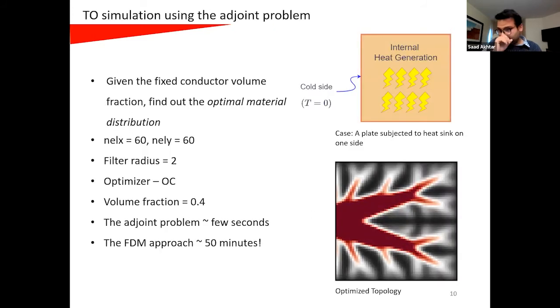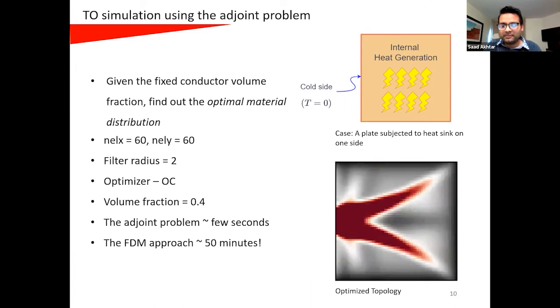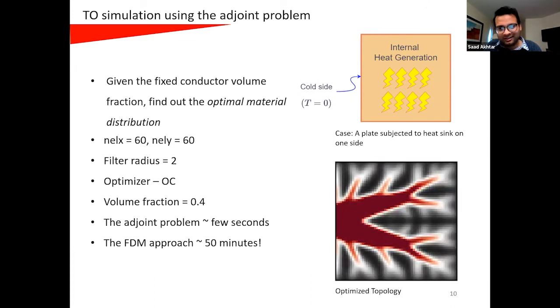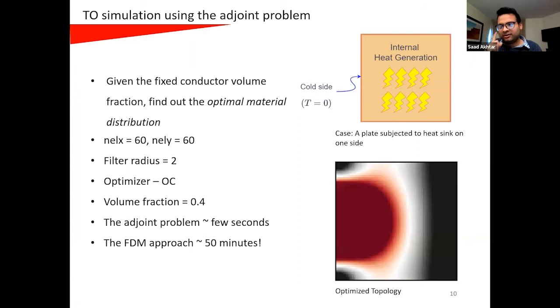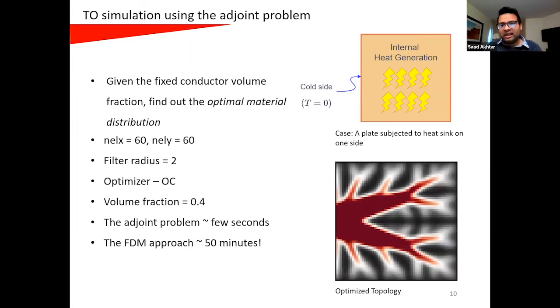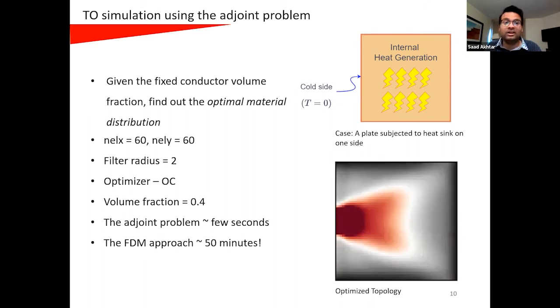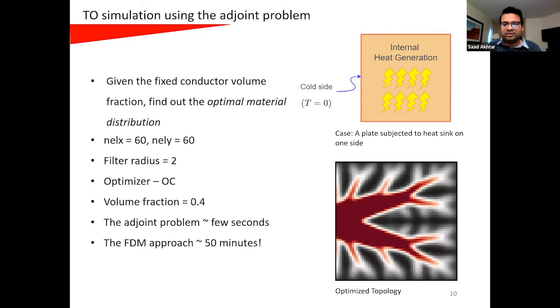Let's see, it's here. Yeah. So we also calculated the sensitivities using, what should I say, finite differencing, which is a very crude way of measuring sensitivities, but it requires constant iteration of the FEM problem for each grid point, and if you scale up your grid, that could be very costly. You could penalize your cost a lot. So just to demonstrate, how the topology.